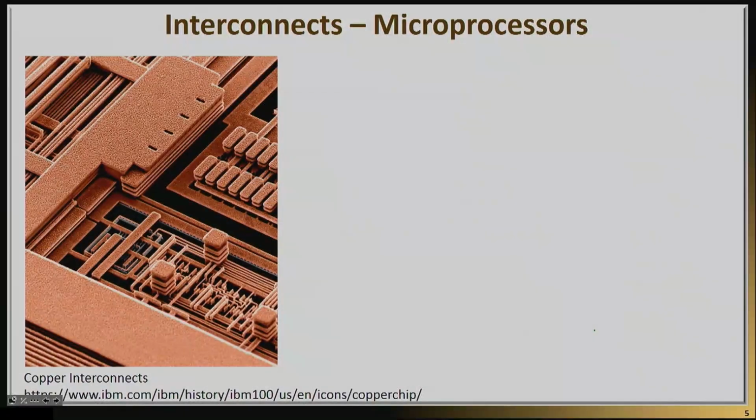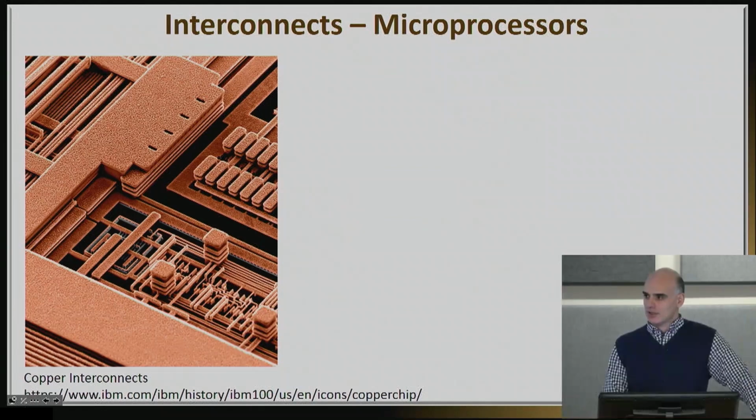Before we conclude these introductory remarks, I want to give you a little bit of an idea of how some of these ideal scenarios will come into real life. I have actually chosen an example here that we can discuss, which is related specifically to digital circuits, mostly because a lot of you can understand how transmission lines impact RF circuits. But the reality is that after we got into the gigahertz era of microprocessors, nowadays transmission line theory is actually required to design a digital chip or a microprocessor.